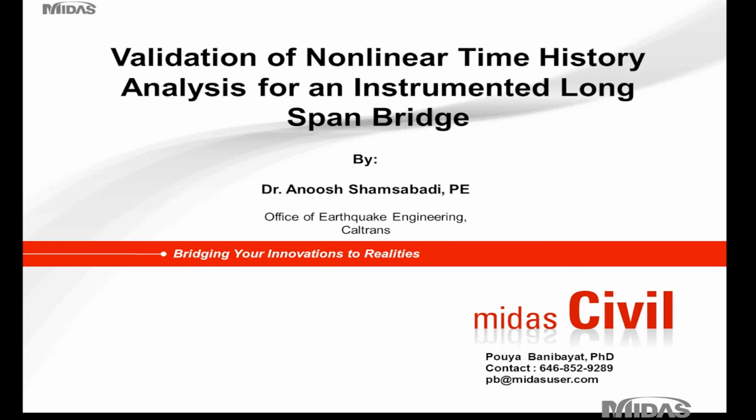Now, that's a very good question. The question is, did you try to use a response spectra as a preliminary design? How close would that be to the obtained results? Whenever you design a bridge, you come up with a response spectra. Not necessarily is the response spectra going to represent the future earthquake that you may see.